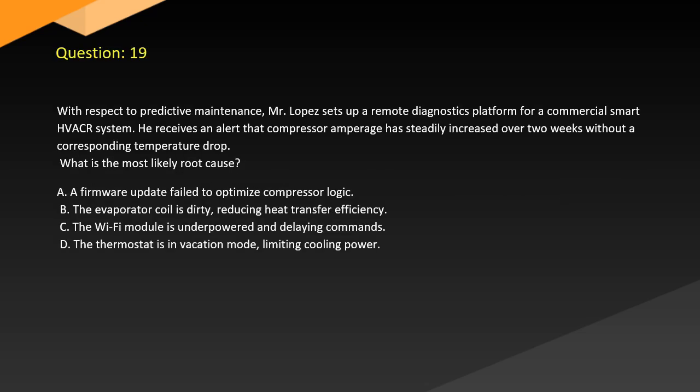Question 19. With respect to predictive maintenance, Mr. Lopez sets up a remote diagnostics platform for a commercial smart HVACR system. He receives an alert that compressor amperage has steadily increased over 2 weeks without a corresponding temperature drop. What is the most likely root cause?